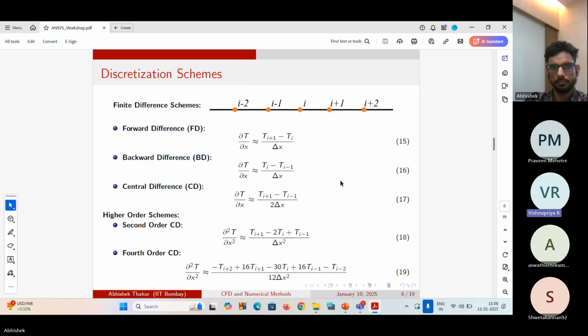Yeah. So here finally, once we do the discretization through I minus 2, I minus 1, what happens after that? We do the different points, we do the different dT by dX, and then what is happening at the end? First, we have divided the domain and we have to find the temperature at I. What is the temperature at point I? Before finding the temperature at I, we have to find what del T by del X is at I, right?